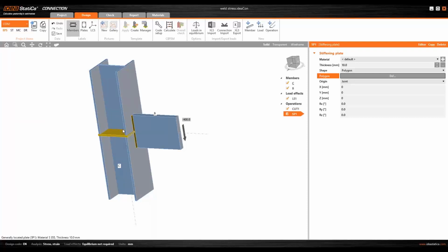So yeah. And maybe I also know that you have to check the units. If your drawing is in millimeters, you have to switch in the import window, as Adam showed, to millimeters, and if you are in meters, you have to be in the same. Yes, units. We cover this transformation during the import, so you can do that. And of course, I want to mention that you can import not only plates, but also different openings, different shapes of openings. It's also possible.